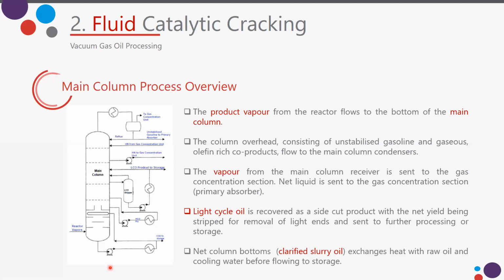Pilar, you know the stream, the second stream from the right hand side, the heavy naphtha from the concentration is back to the main fractionator. So the question is why we are sending this stream back to the main fractionator rather than send it to, for example, CCR. Yes, because these are like internal streams in the column.